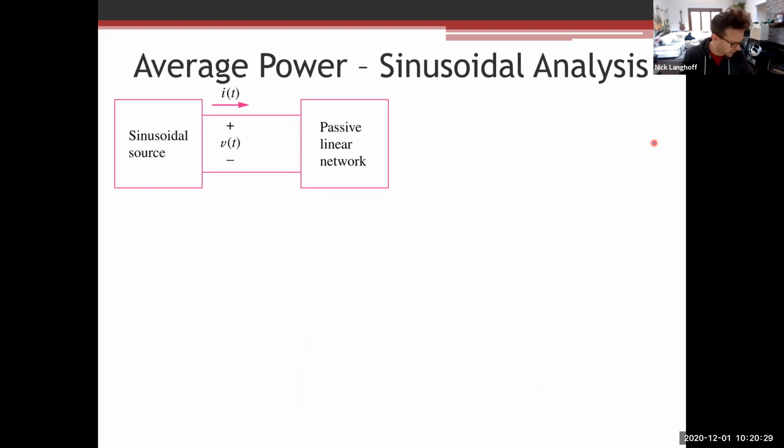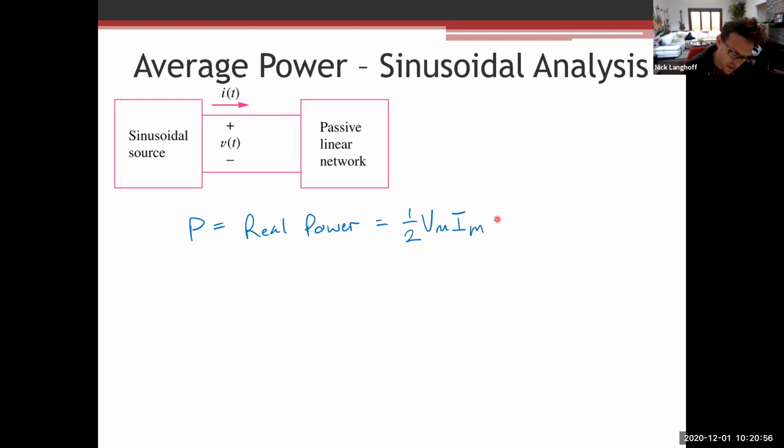So what I'd like to then show, oh my, it looks like I didn't update my notes in this one, but we'll then define these things real quickly. This is just a definition of what we derived on the last slides. We call this the real power. It's also the average power, and it's equal to 1/2 V max times I max times the cosine of theta.